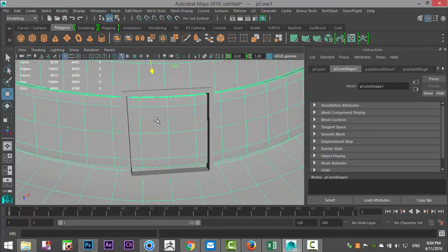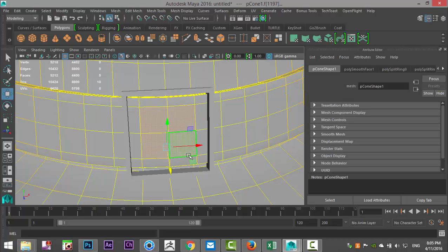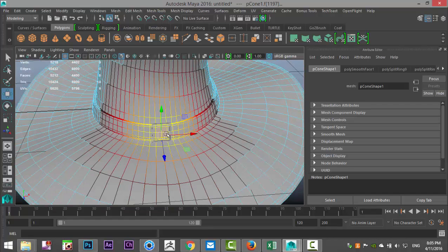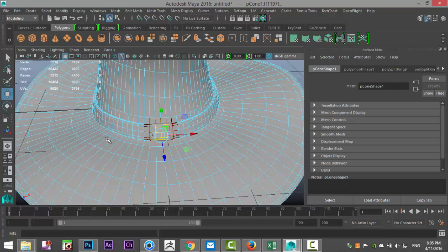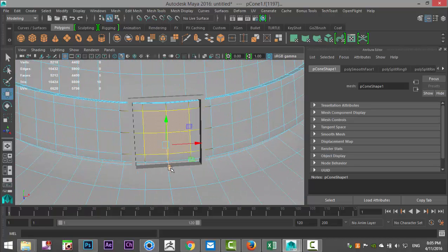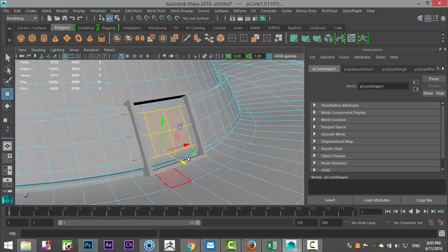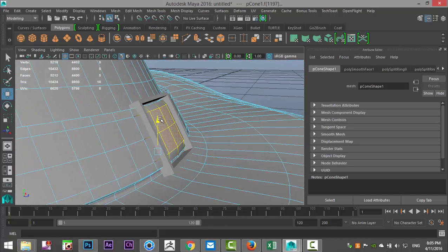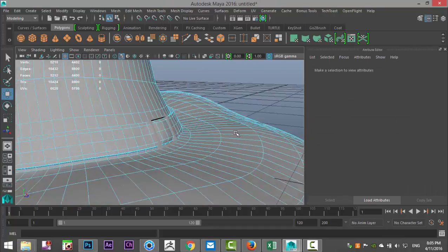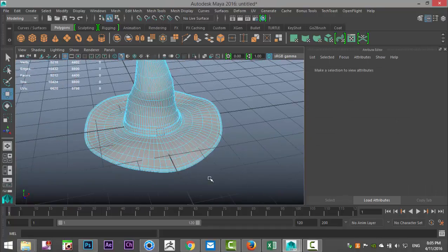Now what we're going to do here is we're going to right click at a face, select these 4 faces, hit B for my soft select, hold down B and left click and drag to decrease the impacted area. And then we're going to just pull that out a little bit. All right. So that's what we have.